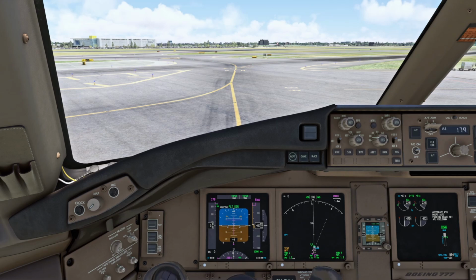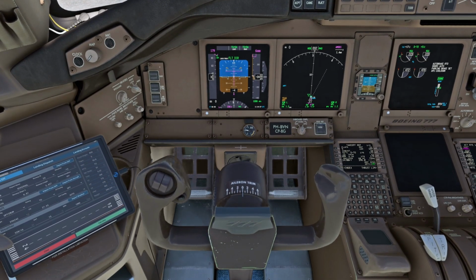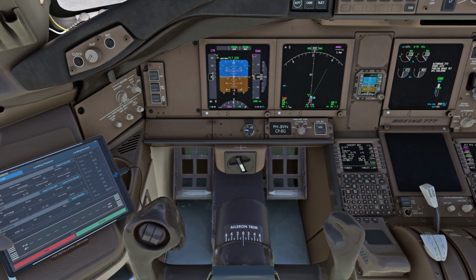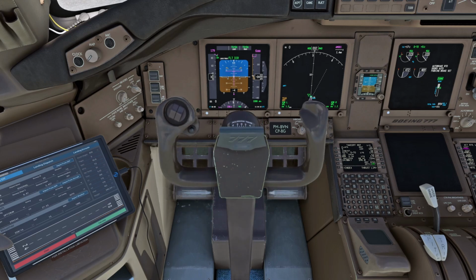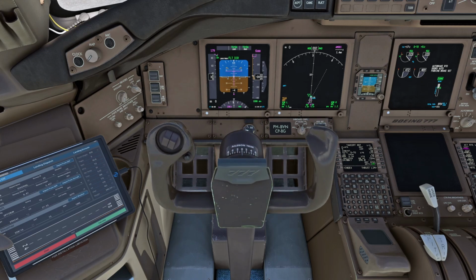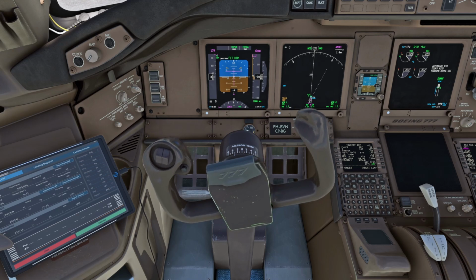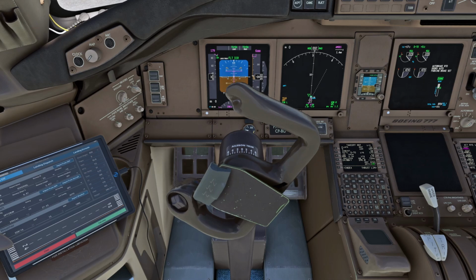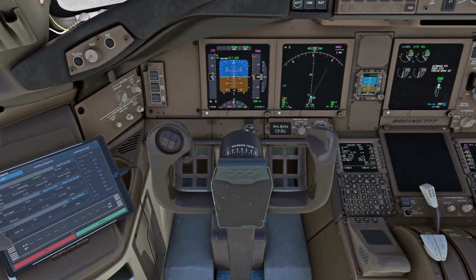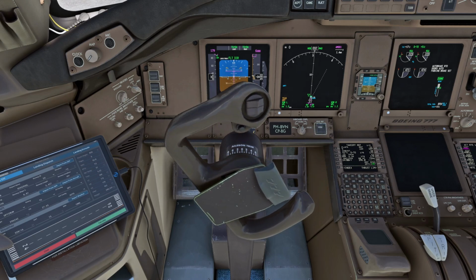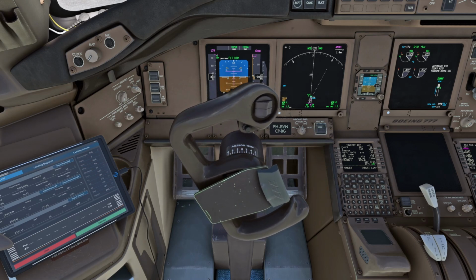And the purpose of the flight control check is really to just check the freedom of movement of the flight controls by pushing the yoke nicely forward and of course all the way back. In real life especially, you have to do that quite slowly, because if you do this way too quickly, it will actually cause quite a lot of shaking in the airplane because of the effect on the stabilizer. So do it just slowly and deliberately. Make sure there's enough freedom of movement. Make sure that the controls nicely center back to their neutral position. And also it's nice to make sure there's nothing jammed and no ATIS messages pop up regarding the flight controls, for example.